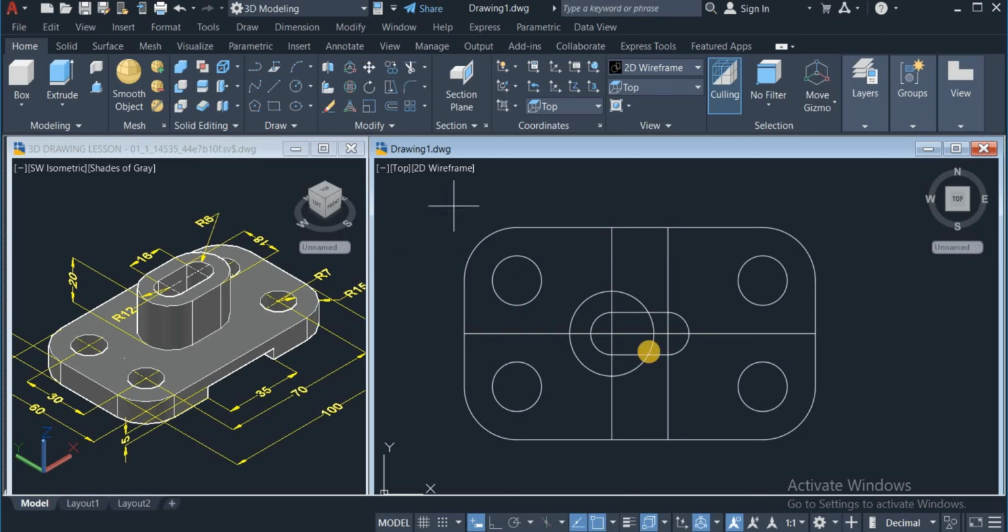Click on the circle command. With here at the center, enter 12 again. Now use the line command again and connect these two circles at their quadrant points. Enter. Draw another line from this and exit this command. Alright, so with the trim command again, I'm going to trim off some portions there.